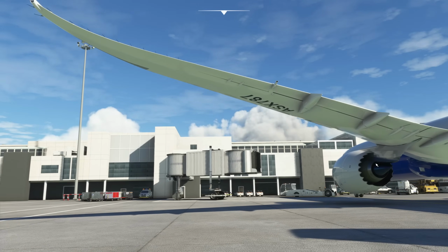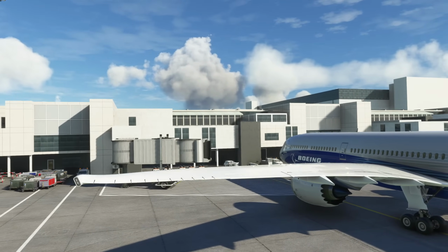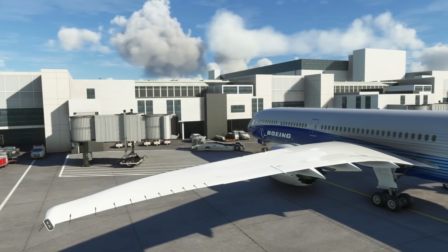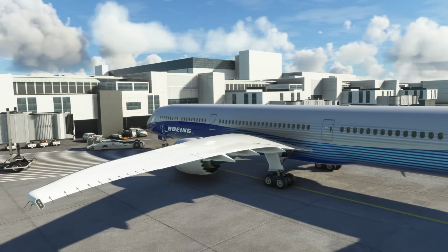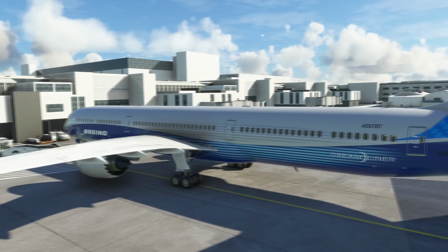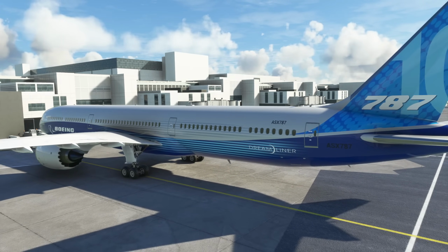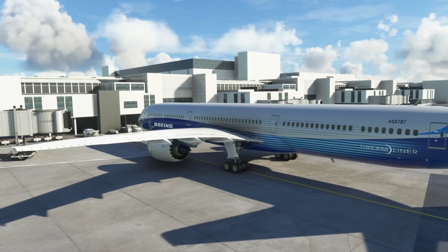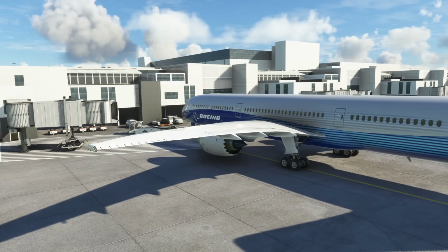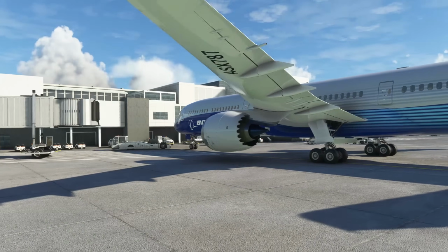They are hydraulic after all. Most of the flight controls are hydraulic. Flaps and gear are hydraulic, but it does have some electronic controls around, such as the electronic stabilizer. So that is electronically controlled. Again, more advantages if you have a triple hydraulic failure. This aircraft does have three hydraulic systems, each one capable of flying it, and even if they all fail, it can still fly, which I think is an amazing piece of engineering. It's a very, very capable airplane indeed.